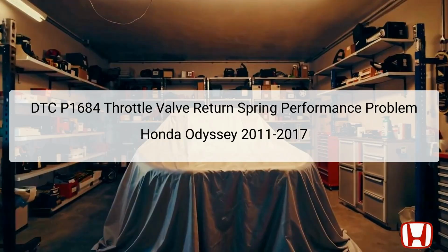The diagnostic trouble code DTC P1684 indicates a throttle valve return spring performance issue in the Honda Odyssey, model years 2011 through 2017. This error relates to the throttle valve mechanism that regulates airflow into the engine, impacting engine performance and responsiveness. The throttle valve is mounted on the throttle body, located between the air intake and the engine's intake manifold. When the throttle valve is functioning correctly, it opens and closes in response to the accelerator pedal position, ensuring